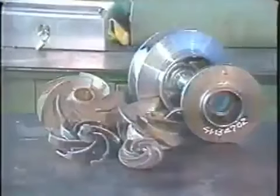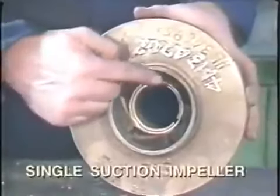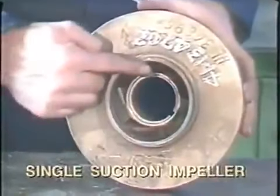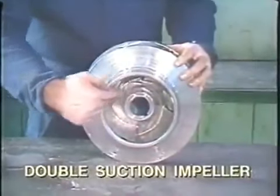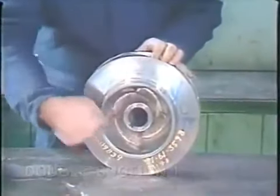However, the discharge nozzle may be positioned in any angle or direction to accommodate piping. Just as there are variations in casing design, there are also several types of impellers. Impellers are first classified by inlet design, either single suction or double suction. In a single suction impeller, liquid enters the suction eye on only one side. For the double suction impeller, the liquid is allowed to enter on both sides. It's really like two single suction impellers placed back to back.